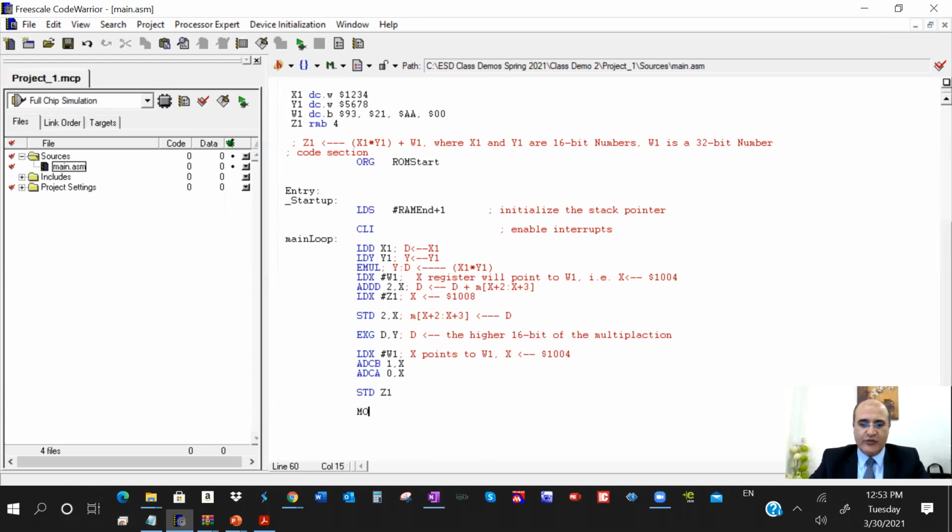So let's turn the 7-segment LEDs on and the red, green, blue LEDs. The red, green, blue LEDs, if you check the schematic, are connected to port P. So for the 7-segment display, move byte immediately $FF to DDRH, to make port H output, just to see something on the board. We put 1s in all the bits.